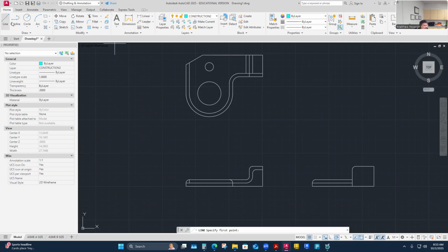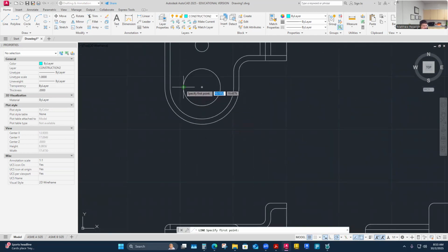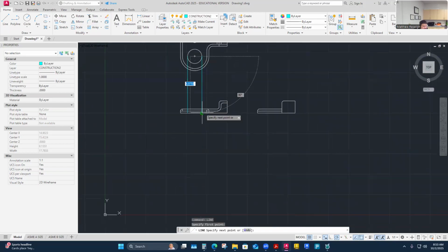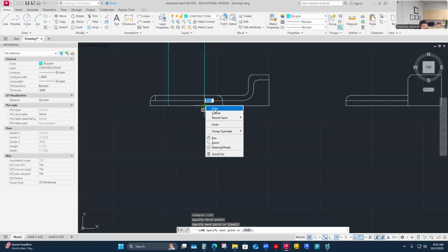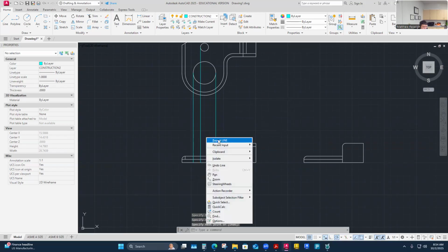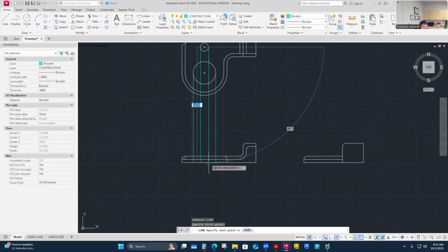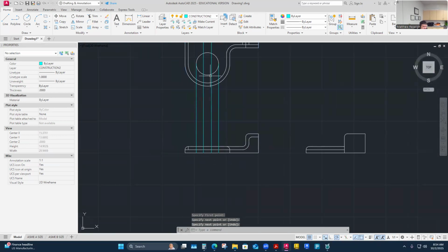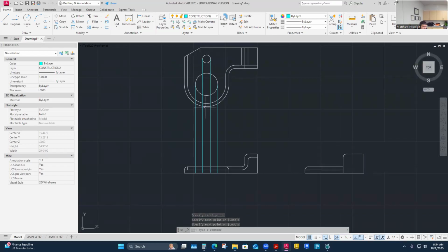Yeah, I think I will project over from the top to the front. This is going to be hidden through the part. This one too will be hidden through the part, so it'll be a little confusing there. I'll kind of have a center line. Oh, they are on center. So actually, the center line carrying the large one and the other one, they are on the same center line this way. So it'll just be a single center line for both those holes.